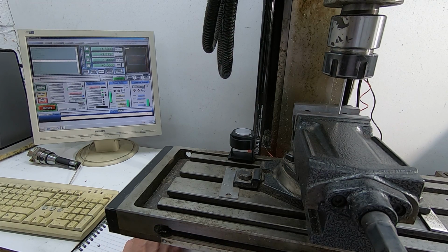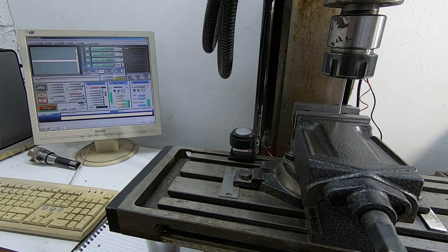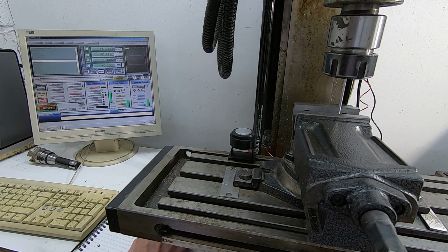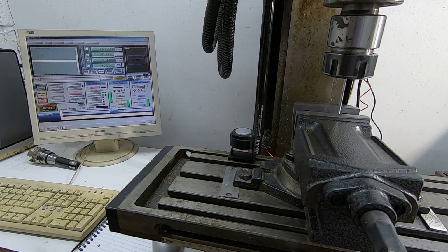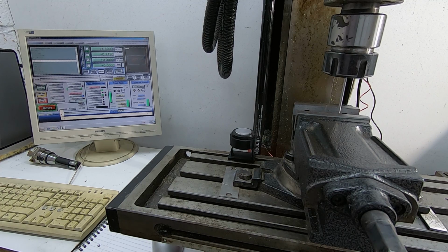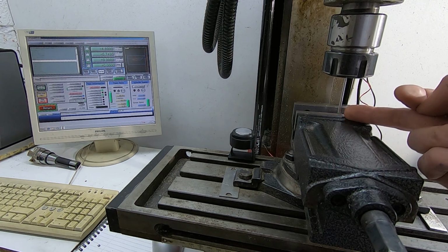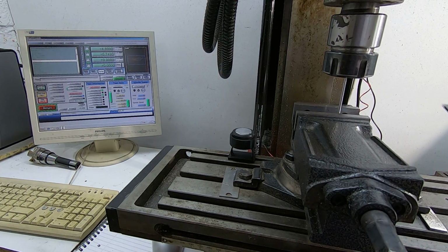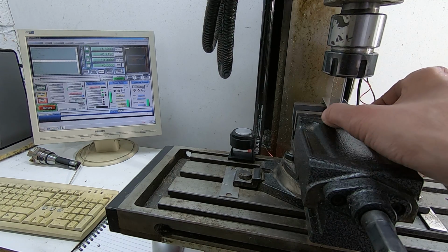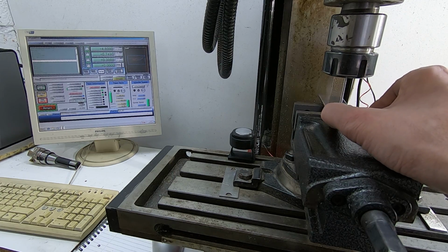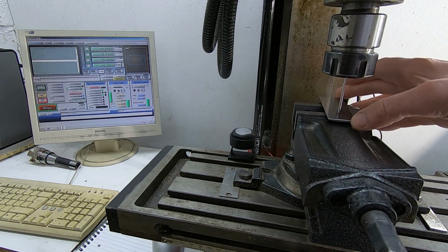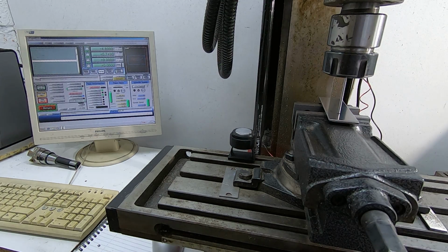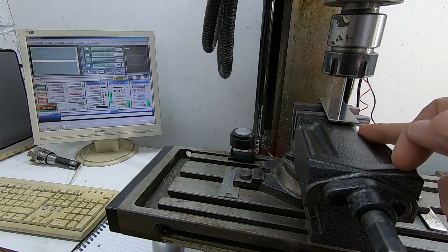I'm going to stop it as soon as it does that. Okay, so it's moved down. I'm going to manually change the Z axis back to 0. So I'm going to just enter Z0. So we now, in theory, should be back in the exact same position as far as the tooltip is concerned to where we started. So I put our plate back in. Remember, there was just a small gap. So we're back now to exactly the same position we were as far as the tool tip is concerned before we started the milling operation.